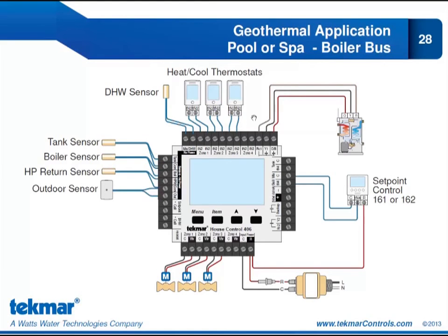Now I don't need a heat-cool thermostat in order to do radiant heating and cooling. A heat-only thermostat is able to send a floor cooling call to the 406. But I'm choosing to use a heat-cool thermostat for this application because it is those thermostats that have a built-in humidity sensor.